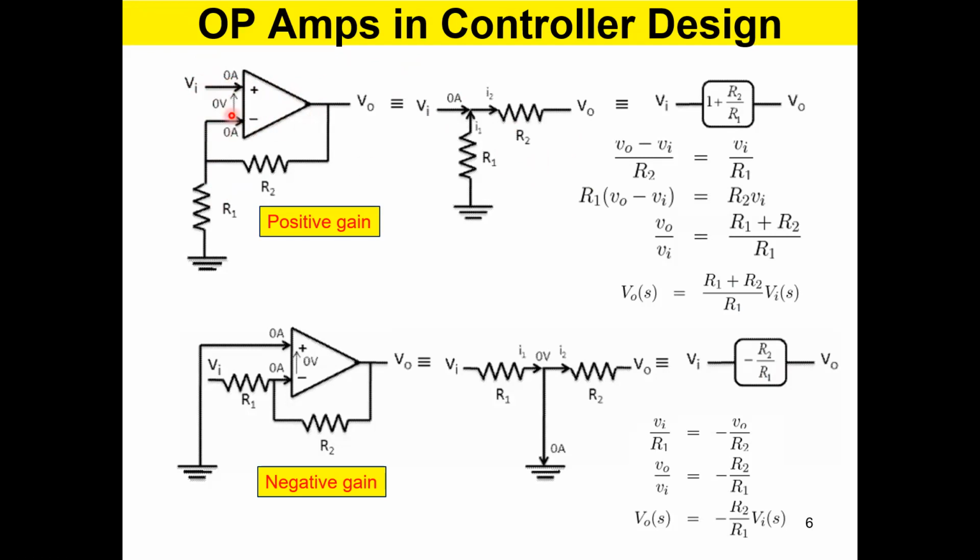When there is no significant voltage difference between these two terminals, it means that when you connect a voltage to one terminal, the internal electronics will raise or lower the voltage of the other terminal so that they are equal. This adjustment happens internally so that the voltage difference between the two terminals will be insignificant, right?